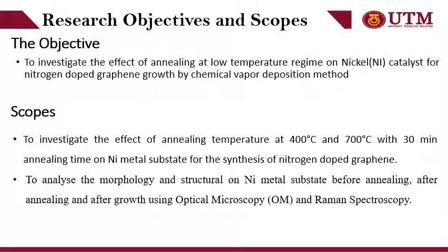The scope of my project is to investigate the effect of annealing temperature at 400 and 700 degrees Celsius with 30-minute annealing time on nickel metal substrate for the synthesis of nitrogen-doped graphene. Next, we will analyze the morphology and structure on nickel metal substrate before annealing, after annealing, and after growth using optical microscopy and Raman spectroscopy.